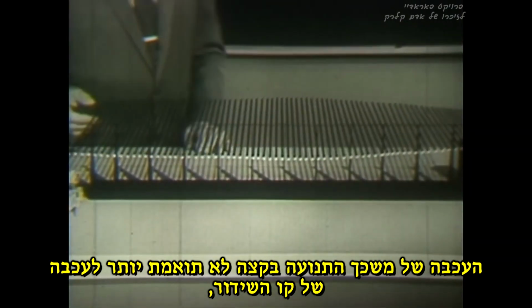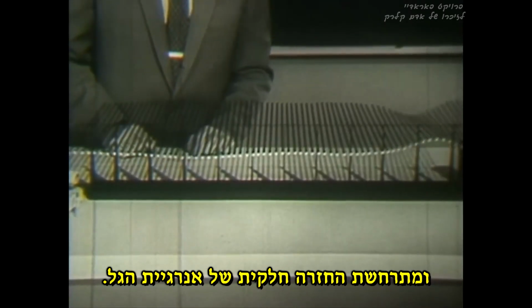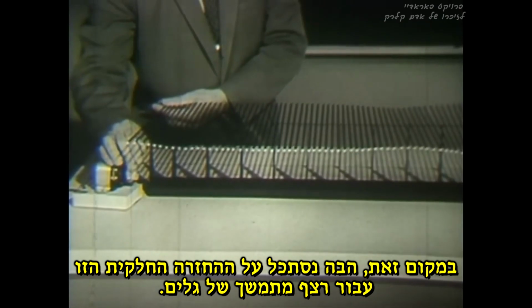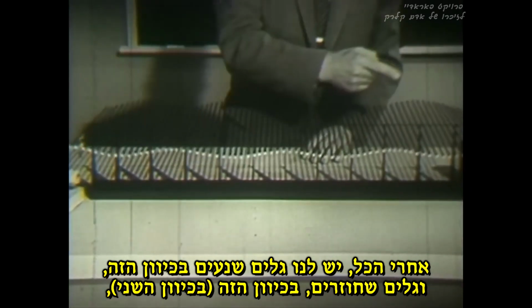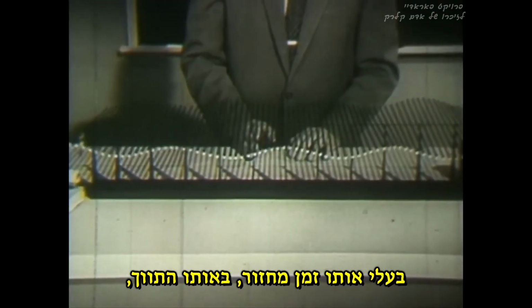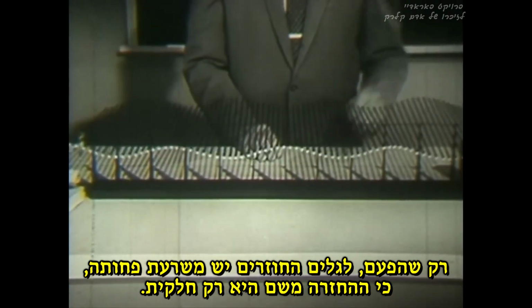The impedance of the load now no longer matches the impedance of the transmission line, and a partial reflection of the wave energy occurs. Let's have a look at this partial reflection now with continuous waves instead. We expect some kind of standing wave pattern to appear on this machine now, don't we? After all, we have running waves going in this direction and returning waves coming in this direction of the same period on the same medium, only this time the returning waves have the lesser amplitude because the reflection down here is only partial.